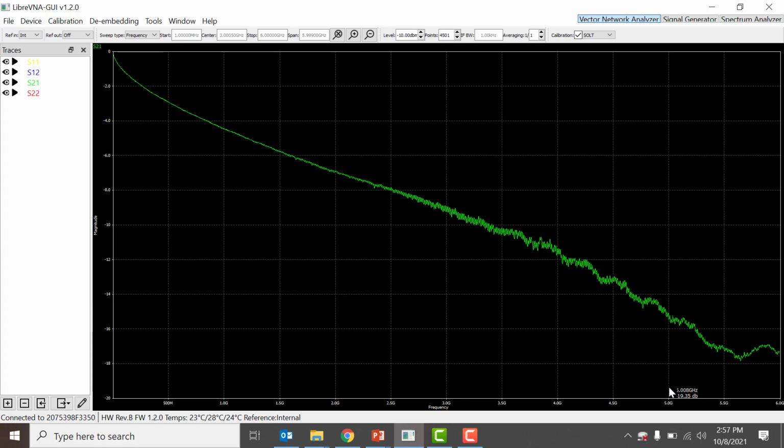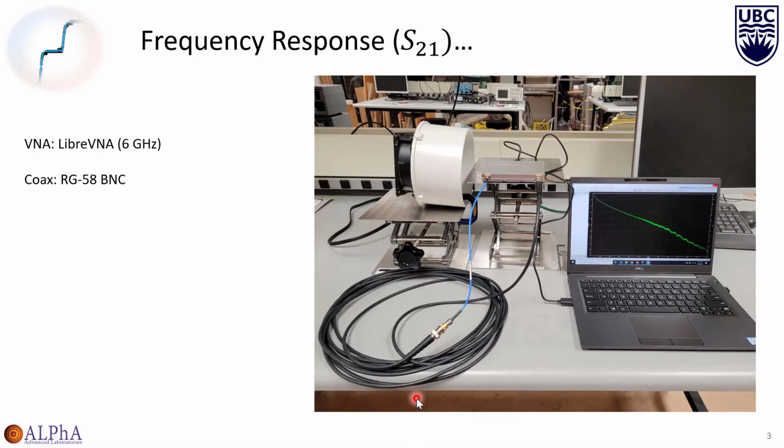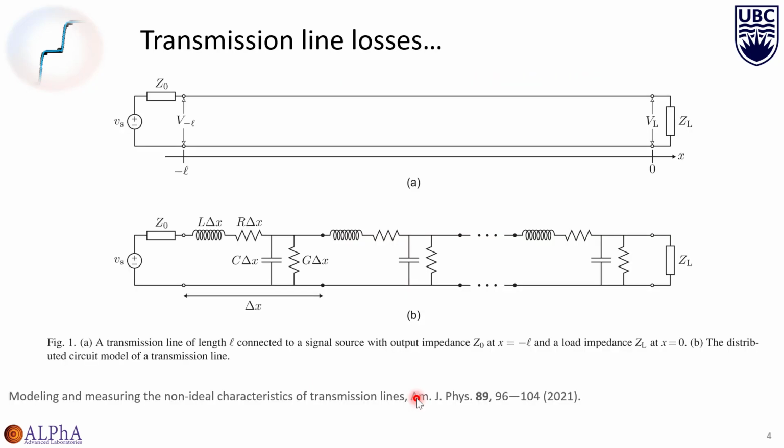And so all of this is just to try to point out that our model of the transmission line that we discussed in class is an idealized model. It's incomplete. So the real model for an actual, non-ideal transmission line would be our signal generator with an output impedance Z0. So that would be like port 1 of our VNA. Here is our load impedance ZL, so this would be like port 2 of our VNA.